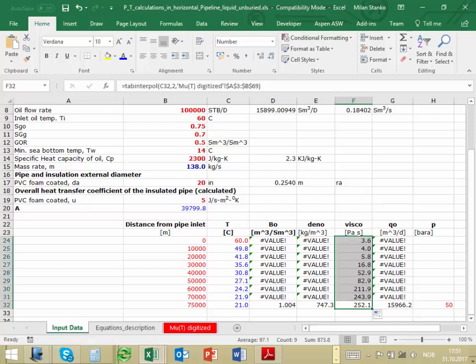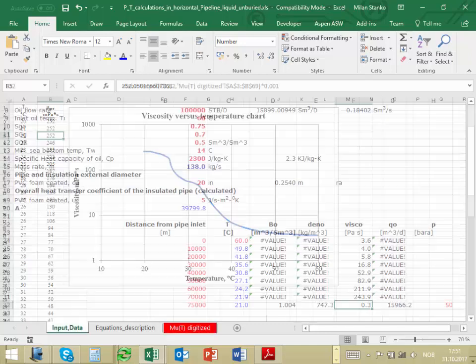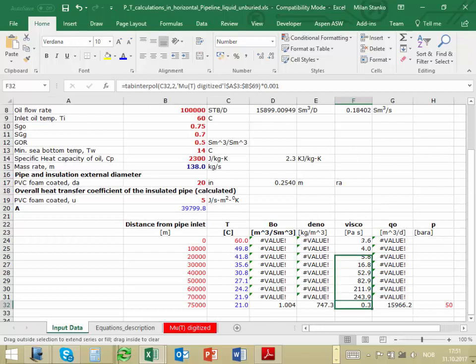We pull it up, okay, and you see why it was important to cut the pipe in pieces, because the viscosity changes very dramatically in the pipe, okay, from, this is centipoise, okay, so here we should times 1e to the minus 3, because that's what we have on the table. It's in centipoise, millipascal second, and we have then to convert to Pascal times second. That's what we need in our expression. Okay, so I pull it up.